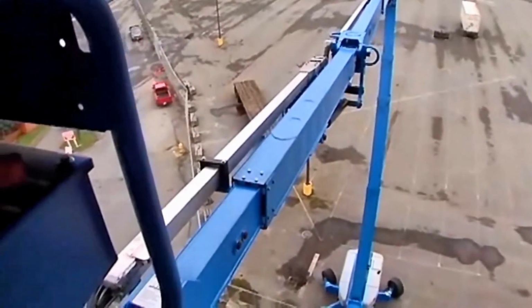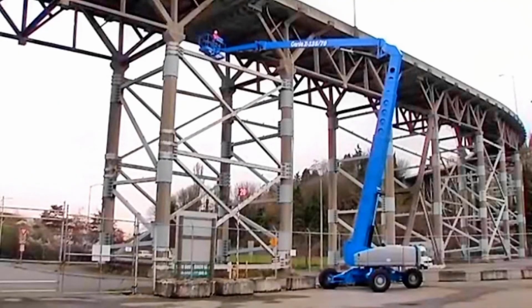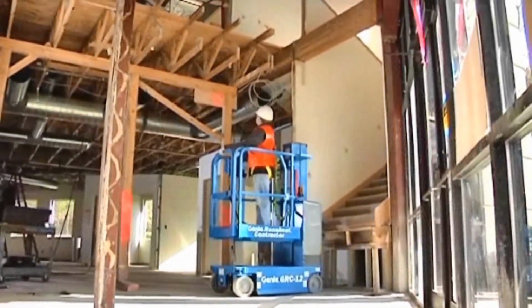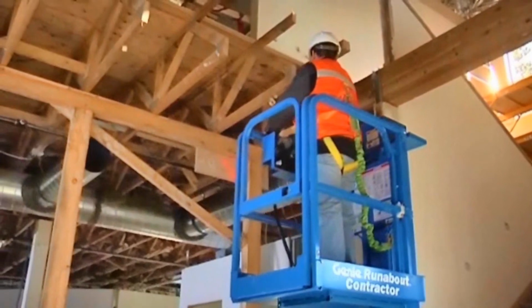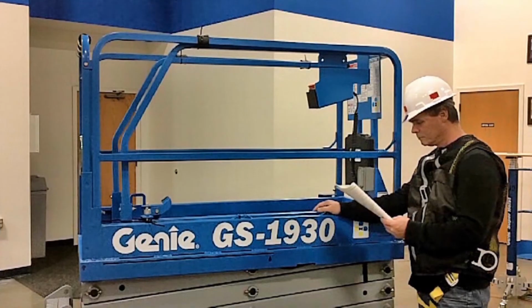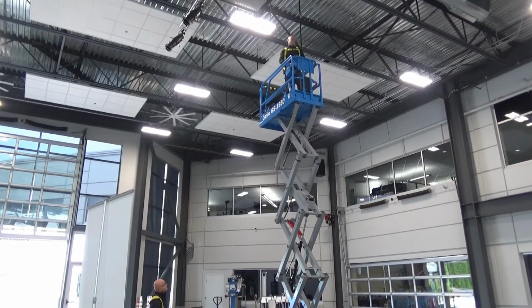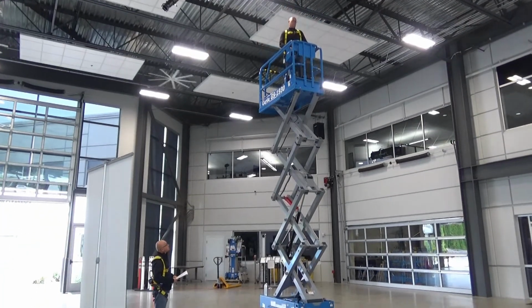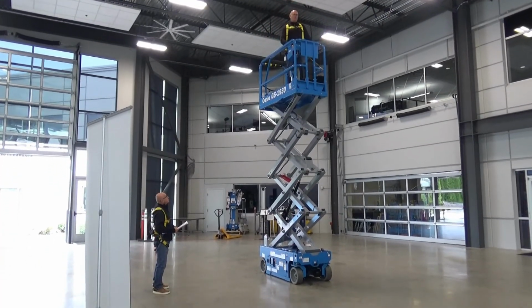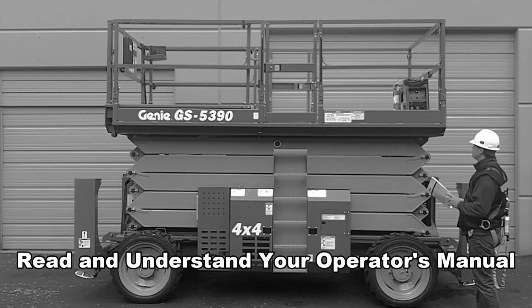If more than one operator is expected to use the MEWP at different times in the same work shift, they must all be qualified operators and they're expected to follow all safety rules and instructions in the operator's and safety manuals. That means every new operator should perform a pre-operation inspection, function tests, and a workplace inspection prior to each work shift. Once you have successfully completed your participant's guide and the written test, you will almost be ready to operate a mobile elevating work platform. Read the operator's manual for the specific machine you wish to operate. Then you must operate the machine for a sufficient period of time to demonstrate proficiency in the actual operation of the machine.